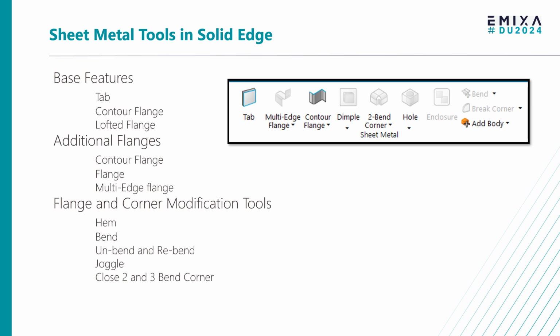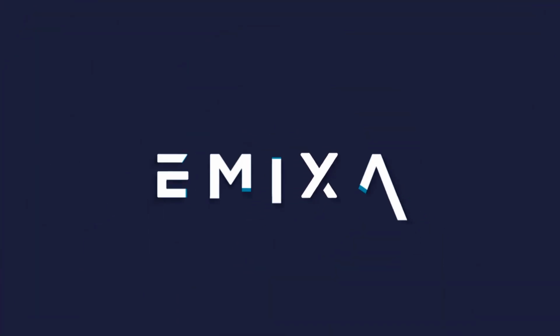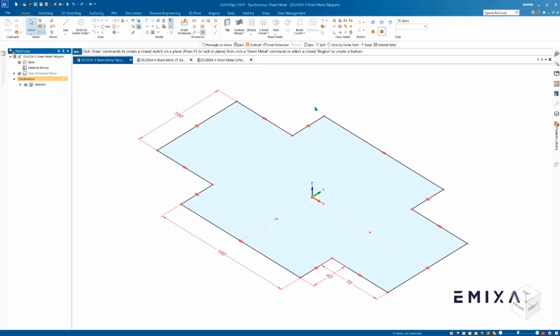We can unbend and rebend, so we can unbend, put a cutout in, rebend it, and see what it's going to look like. We can do a joggle, which creates 2 extra flanges and 2 bends based on a single line, so it'll create 2 90-degree bends, and then we can also close our corners with both 2 and 3 bend corners. So let's have a quick look at those in action.